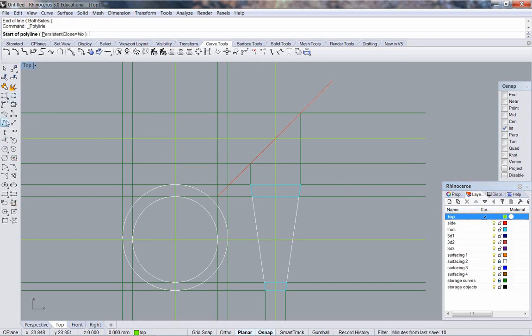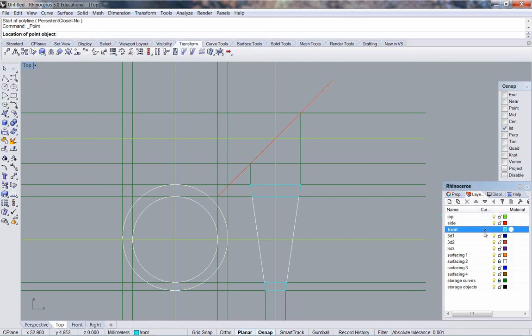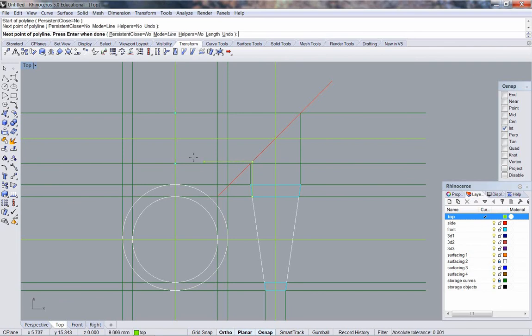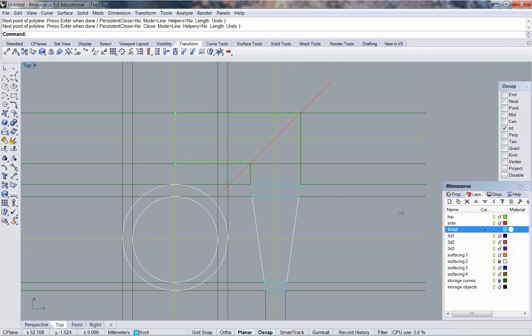So, some construction lines. I already have the maximum width of my top cross section. So I'll go ahead and put points in for that. It's obvious, but I'll put them there anyway. I'm going to draw a construction line for the narrower width. Pull up to the miter line, intersect, carry over to the center construction line, intersect. And that width gets 2 points as well.